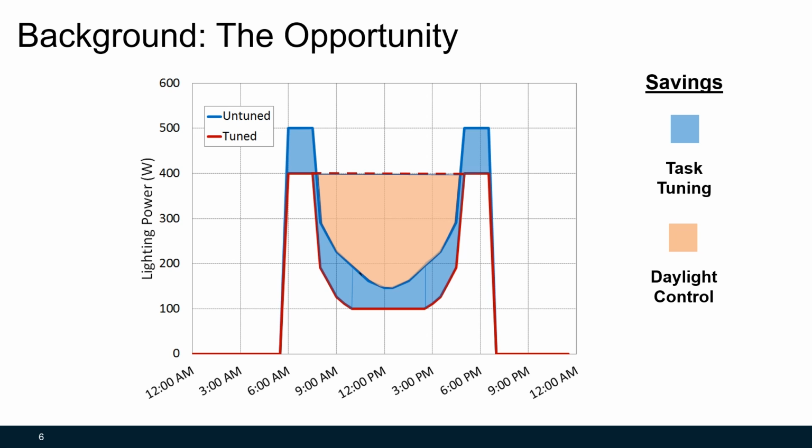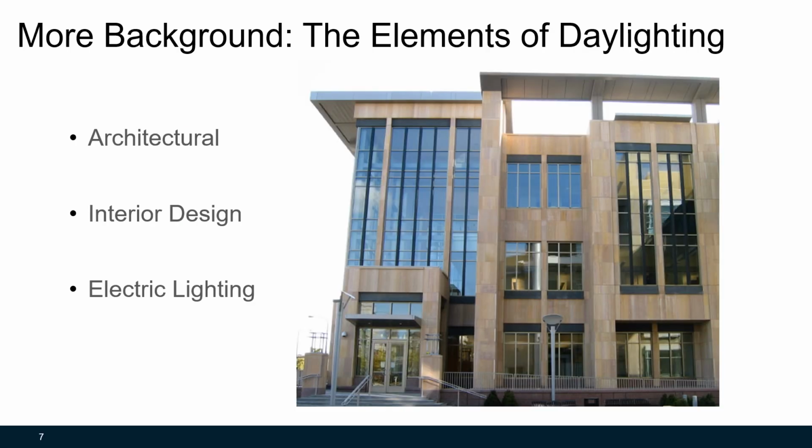In fact, the only time that the energy savings is different from the system without photo control is when the amount of daylight is sufficiently high that the lights are dimmed to near or at their minimum. We will touch on their savings interactivity later. However, it should be noted that since there is less lighting energy to save after tuning, the savings component for daylighting controls is less.